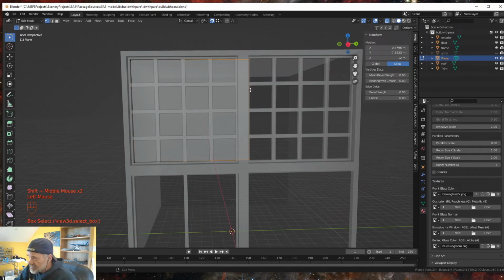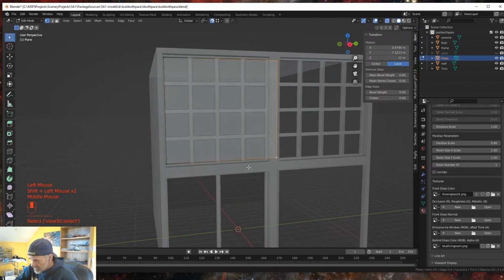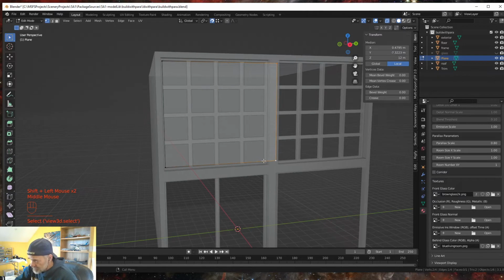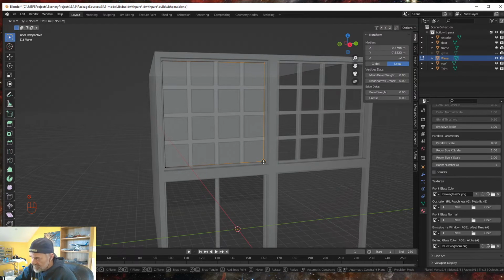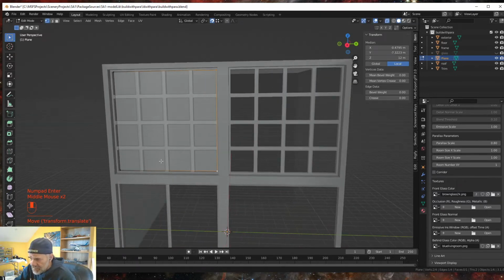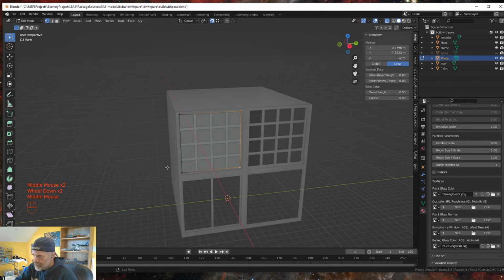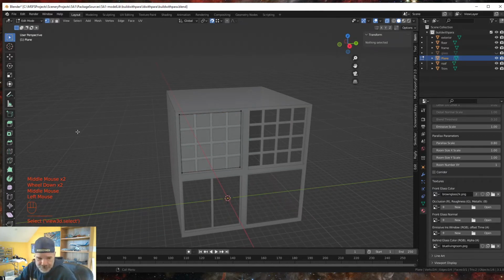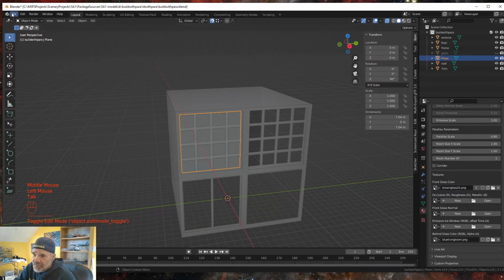Now we're going to select these right ones, hit this bottom right hand corner to control it, and then we're going to hover our mouse over the point, hit G. And then I want to do GY just in case I inadvertently moved my mouse, so that plane is sitting behind the frames. Okay? Now, we get out of edit mode and let's do a save.